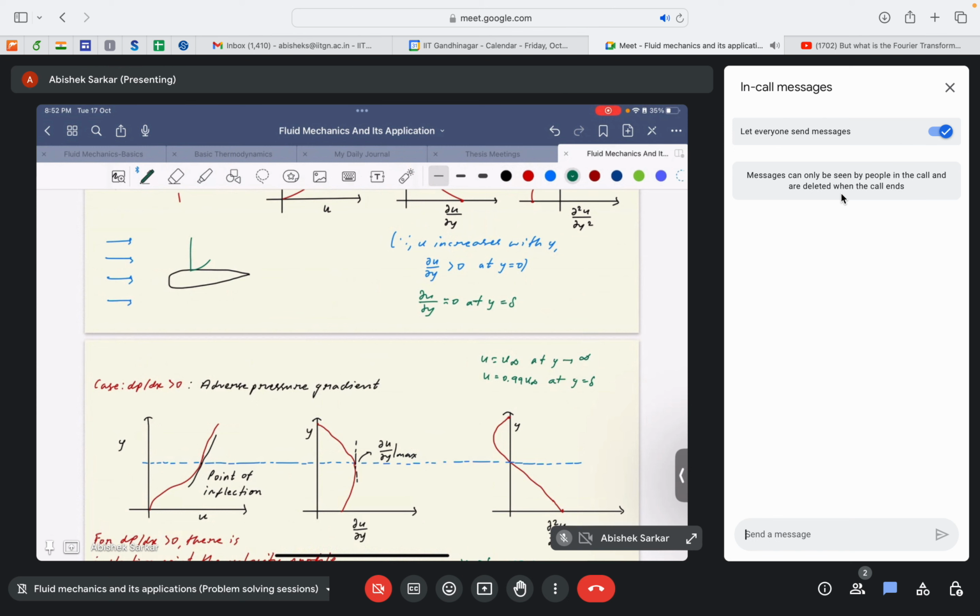Okay, this is rightly observed. This is not something that I am making up. So the velocity profile reaches a maximum value that is usually of the order of the boundary layer thickness, and then it usually reduces to a certain value and reaches a constant value, and this constant value is the free stream velocity. This maxima u max is usually greater than u infinity.